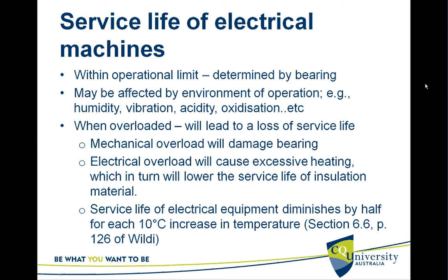But when overloaded, that will lead to a loss of service life. Now mechanical overload will damage definitely the bearings. Electrical overload will cause excessive heating internally, which in turn will lower the service life of insulation material. That's the direct impact of overcurrent.